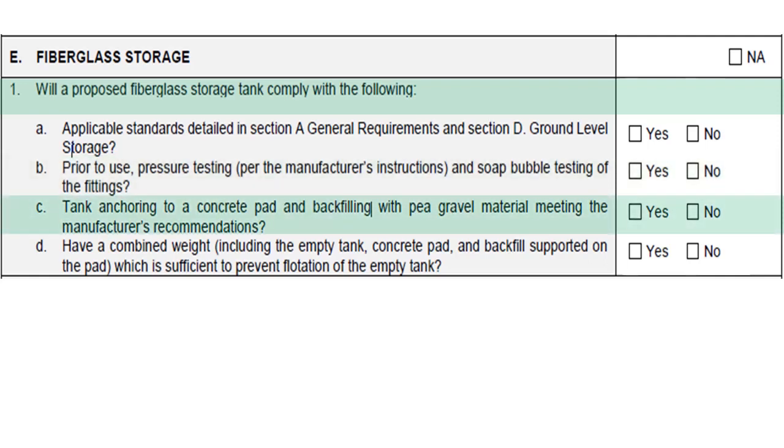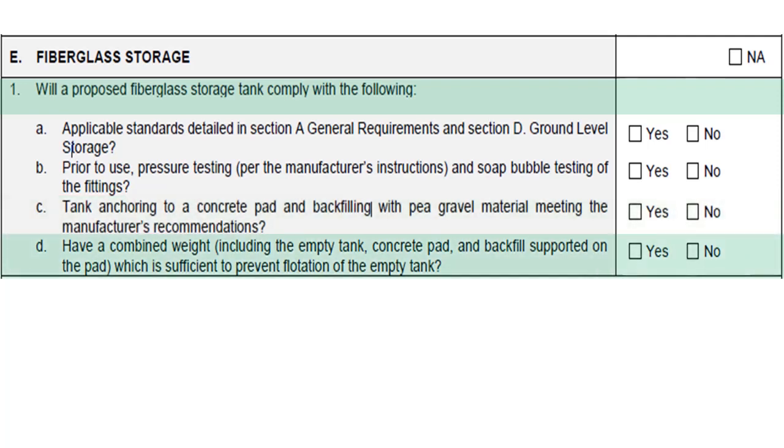Tanks should be anchored to a concrete pad and backfilled with pea gravel meeting manufacturer's recommendations to prevent the tank from floating in the event of a flood. The combined weight of the empty tank, concrete pad, and backfill supported on the pad should be sufficient to prevent flotation of the empty tank.